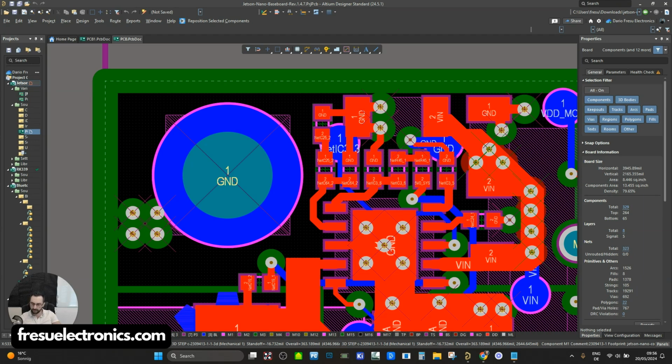So the way that we're going to achieve optimal performance of the power delivery network is by using return reference planes, but also by engineering the power path with the lowest possible inductance and resistance. One of the most efficient ways is to reduce the transient current loops from the power source to the load. And this means that we have to bring the power source closer to the load.